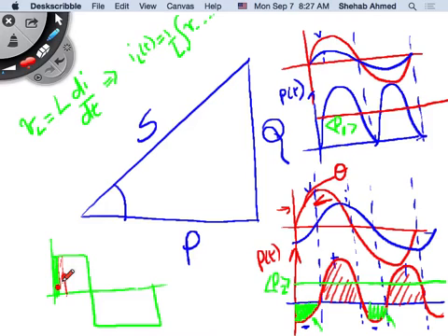If I have a voltage, for current to exist, I'm basically taking these small portions of the voltage and adding them up. So you know that if you have a voltage waveform that's leading a current, or a current waveform that is lagging the voltage, then you have a system that is more inductive than capacitive. And of course, if there is no inductor or capacitor, then the voltage and current are in phase, which is this case, right? So in this case, I have no reactive power. I have a good amount of average power. I also have what? Is this waveform DC?